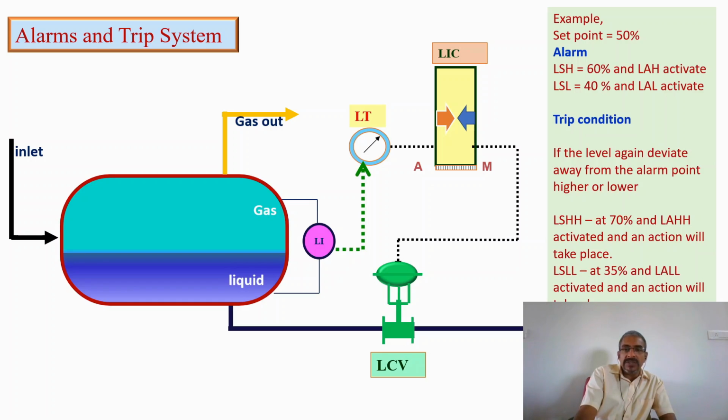Look at the picture. There are two changes coming into the presentation. One is the level switch high activated at 60%. Immediately the level alarm high is activated in the control room. So the operator can go and take the decision immediately, as we discussed earlier. In the same way, a level switch low will activate at 40%. Look at that. The physical instrument switch is there to watch when the level comes around 40%.